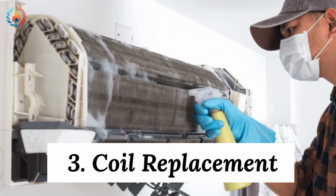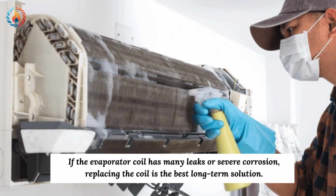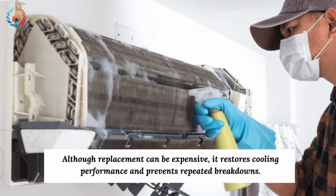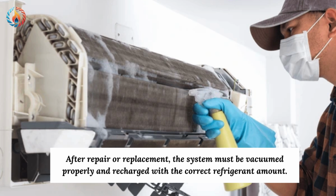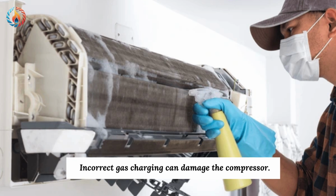3. Coil replacement. If the evaporator coil has many leaks or severe corrosion, replacing the coil is the best long-term solution. Although replacement can be expensive, it restores cooling performance and prevents repeated breakdowns. 4. Refrigerant charging. After repair or replacement, the system must be vacuumed properly and recharged with the correct refrigerant amount. Incorrect gas charging can damage the compressor.